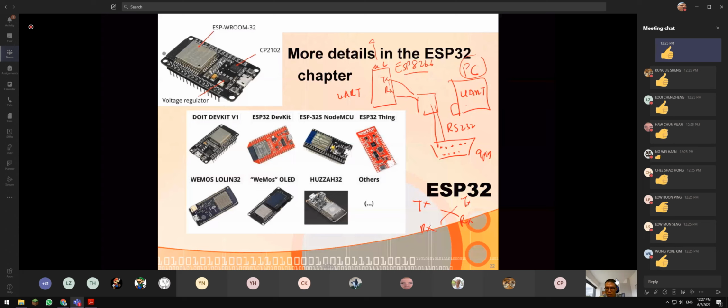Why? Because the ESP8266 runs at just 3.3 volt. However, in the PC, it's about plus minus 25 volt. Just to share with you, in the PC, for the positive region, 3 to 25 volt is considered binary 0, not 1, and -3 to -25 volt is binary 1.